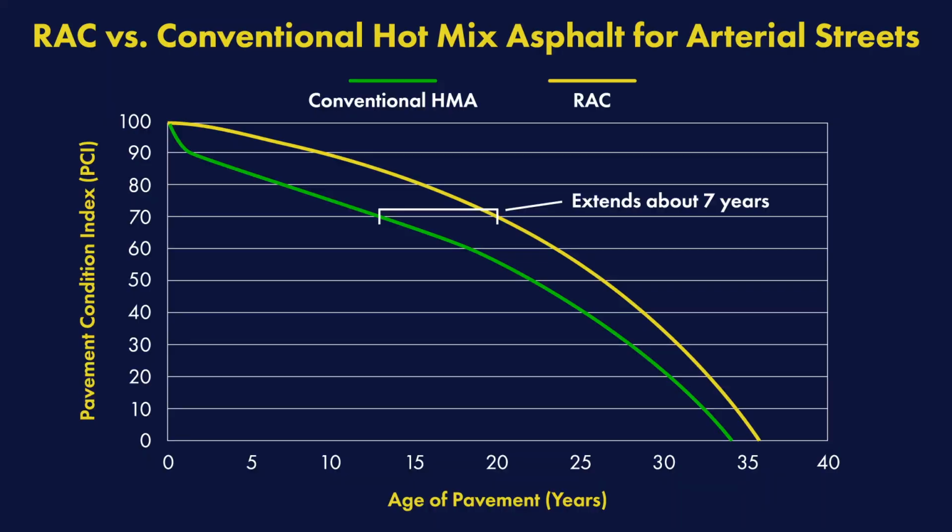In a study of 377 Caltrans and local agency projects statewide, the average of all projects found that in-place RAC costs were about 10% higher than conventional mix. The tonnage and geographic location have an influence on price. However, this slight increase in price is offset from a life cycle perspective by the increased longevity, reduced thickness, and less maintenance RAC provides.